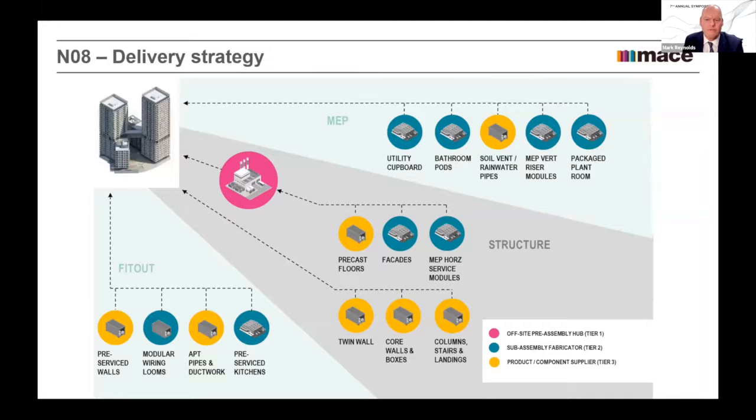So the concept is we very much look at the BIM and taking a BIM model, but we use what we call the federated model, we use system trees, a bit like Mutu showed. So we break everything down into the sub-assemblies, and we only look at sub-assemblies when they add value, and we look at materials and components. So we break all this down into a system tree that we can then track the sub-assemblies, the cost of sub-assemblies, the bill of materials in those sub-assemblies.